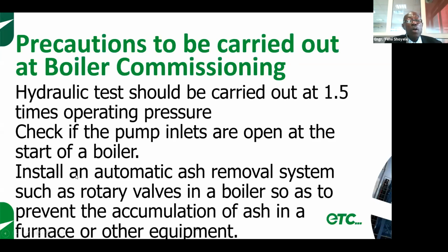Now, install an automatic ash system. Make sure that it's an automatic ash removal system. Remember that in fire tube boilers, particularly, you do not have the luxury of going in and out of the boiler, except when you're doing a shutdown maintenance. So at certain intervals, you have to have the ash in the furnace removed.